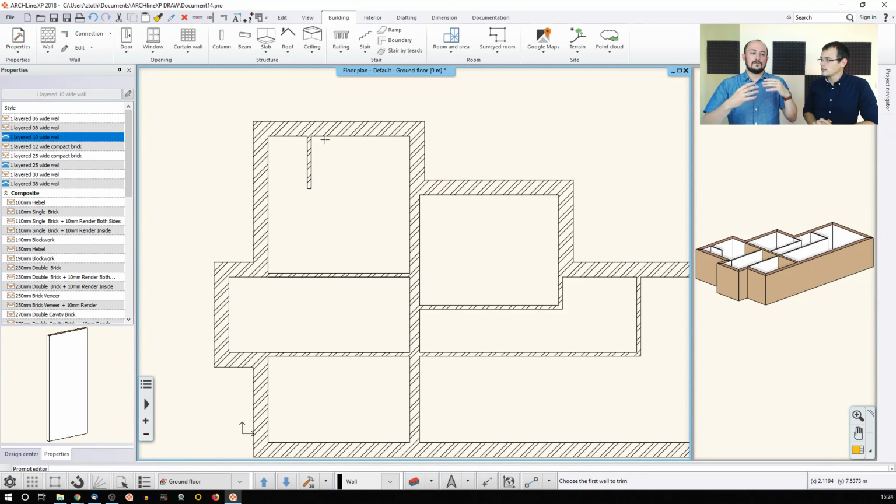Yes. Because the first clicked item will change its length to match the other item. So it extends into the other thing. If I do the other way around and I say, okay, T-connect this into this, something else will happen. The length of this wall changed, but it cannot ever meet with the second wall without modifying it. But that's the point here. The T connection modifies only the first wall and not the second. It just modifies the length and tries to match the walls, but if it's not matching, then it's just changing the length.